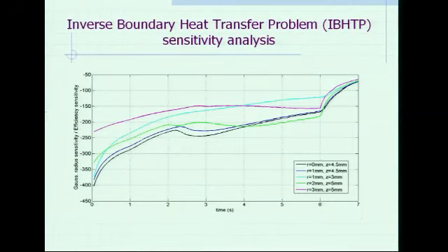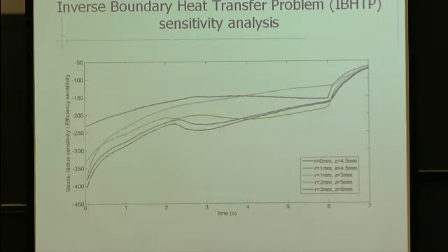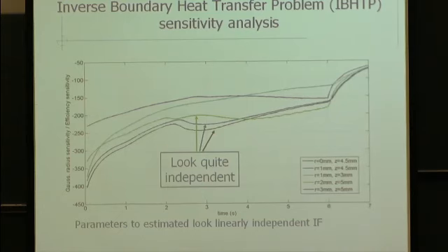So when I do this ratio, I compare for the 5 points, this is the 5 points where I measure temperature, and these are the coordinates. For me, the most interesting points, where the ratio is quite varying between the two sensitivities, are these 3 ones, the first 3. So it is at these points that it seems we are quite independent, and I can perform the estimation in this method and build my sensitivity matrix. So I will use these points next to estimate my parameters.